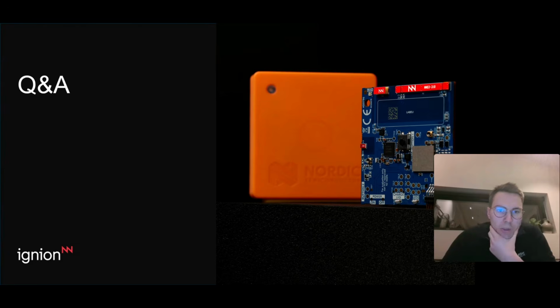According to the system level design principle, effective isolation is essential for the simultaneous operation of Bluetooth and Wi-Fi at 2.4 gigahertz. While various techniques exist to mitigate interference between these two radios, they often involve trade-offs that impact throughput performance for both Bluetooth and Wi-Fi. Therefore, I would like to understand what constitutes a reasonable level of isolation, as well as the maximum achievable isolation when designing Bluetooth and Wi-Fi antennas on the same PCB, specifically one that is 200 millimeters in length.